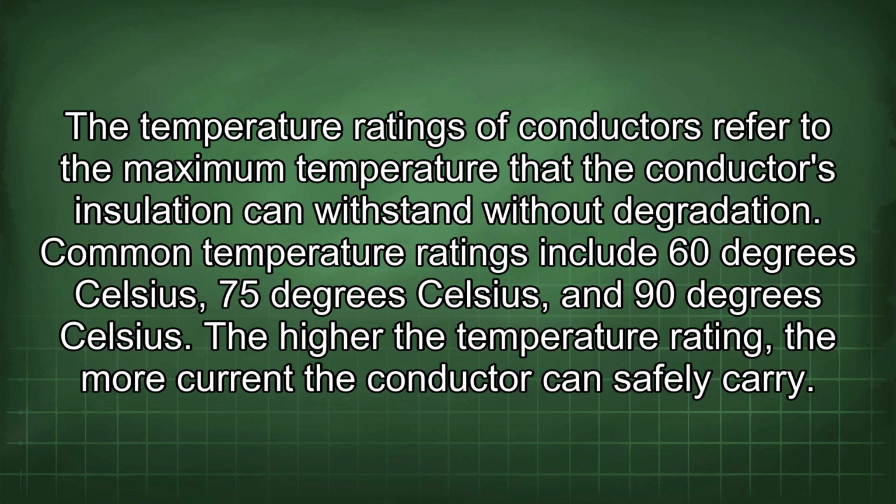The temperature ratings of conductors refer to the maximum temperature that the conductor's insulation can withstand without degradation. Common temperature ratings include 60 degrees Celsius, 75 degrees Celsius, and 90 degrees Celsius. The higher the temperature rating, the more current the conductor can safely carry.